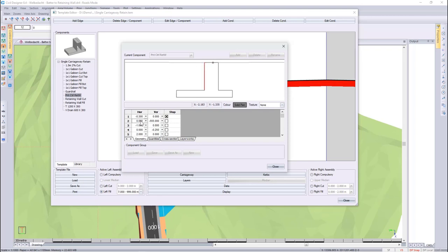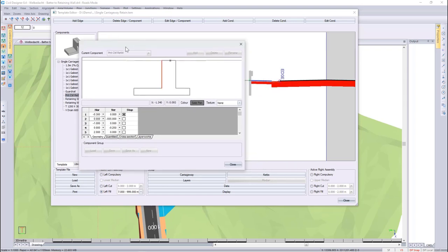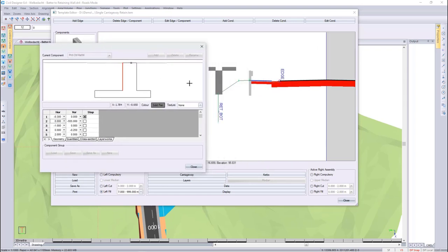Then looking at these special vertical movement codes, our retaining wall is going to be worked from the top down to the bottom. If you are happy with that, you make this special code a positive sign. If you make it a negative sign, it means that you're inverting the direction.